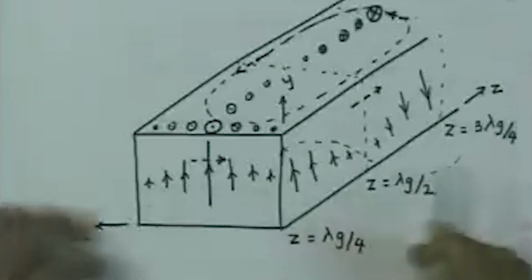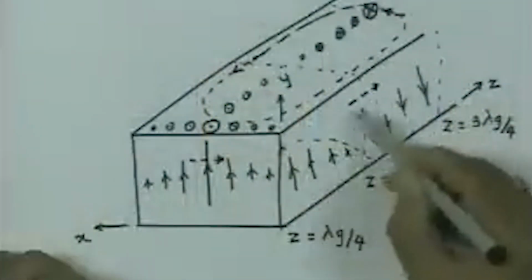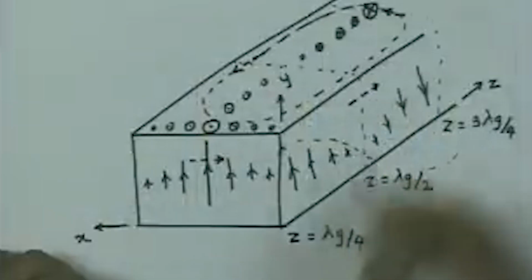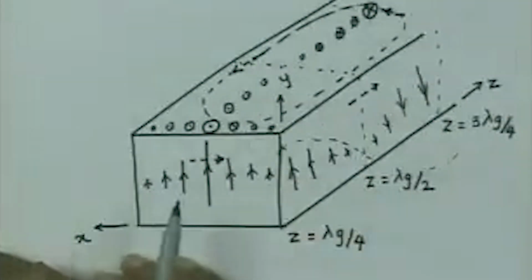However, if I have a current probe which can excite magnetic fields, then putting the probe on this wall would not help, because at this location the magnetic field is not really good, the magnetic field is here. So, if I put a current probe which can excite this field, then this will help in exciting TE10 mode inside the waveguide.